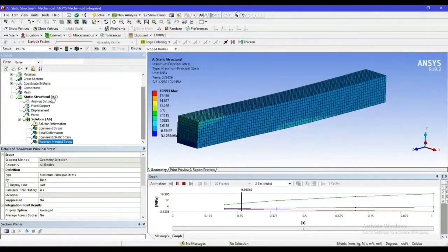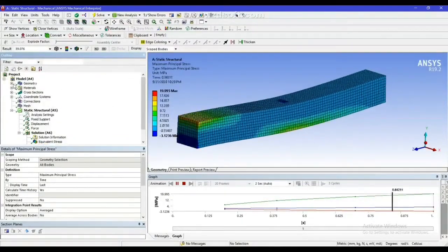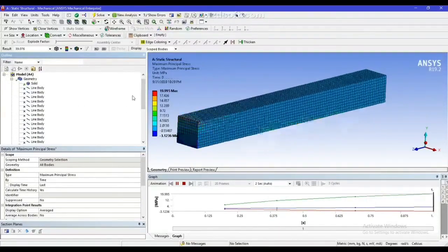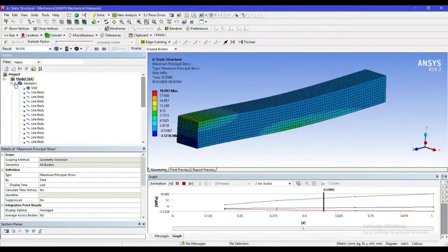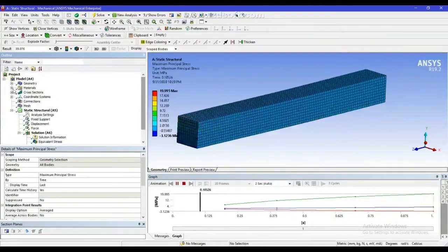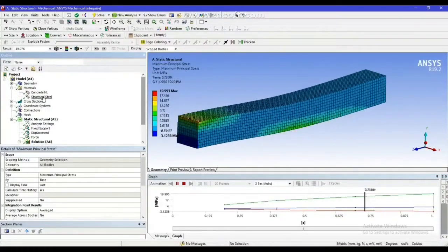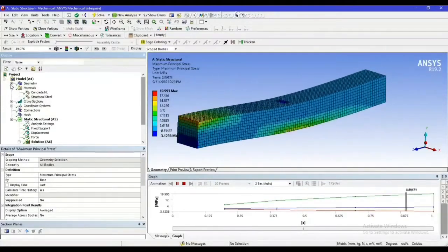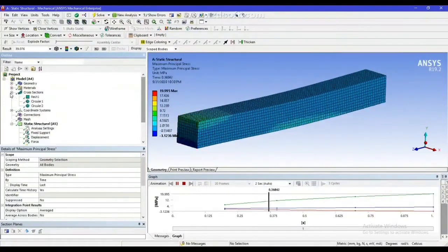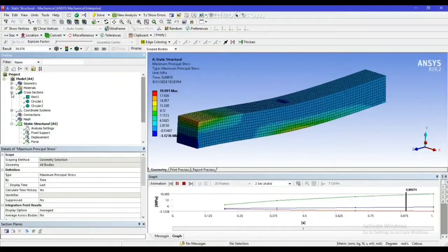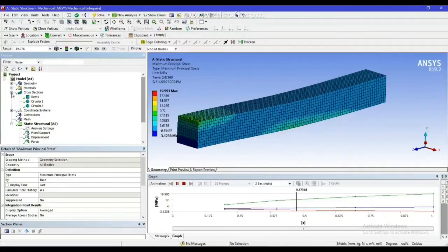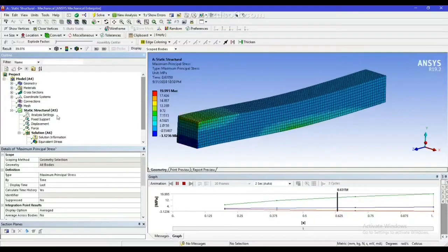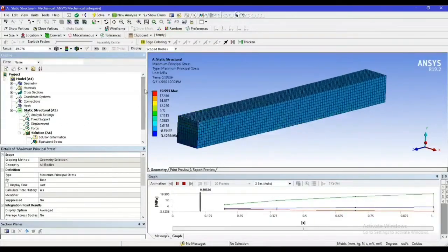As you see from here in the project tree, we try to create this reinforced part by using different tools in Ansys Workbench, and you can also see that you have to select the material for concrete, rebars and stirrups. Besides this, you have to select some cross-sectional area. By the way, this will be clear when we do everything step by step.